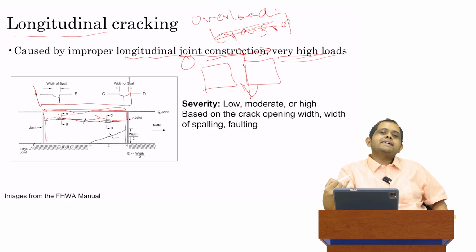However, enforcement in India tends to be somewhat weak. And I'm sure all of you have seen those large trucks which have a very large amount of material, agricultural material typically, but they are overloaded. So when those types of vehicles regularly go on the road, they can create a high stress at the surface, which in turn leads us to getting some type of longitudinal crack like this.